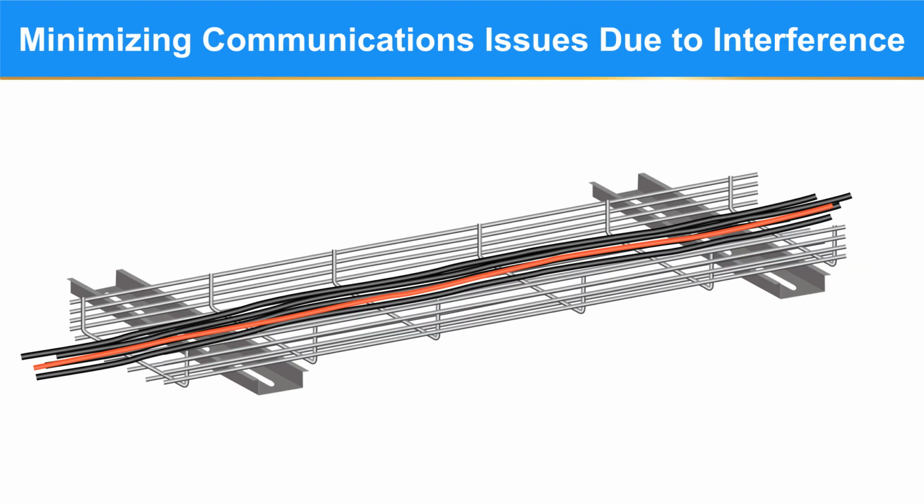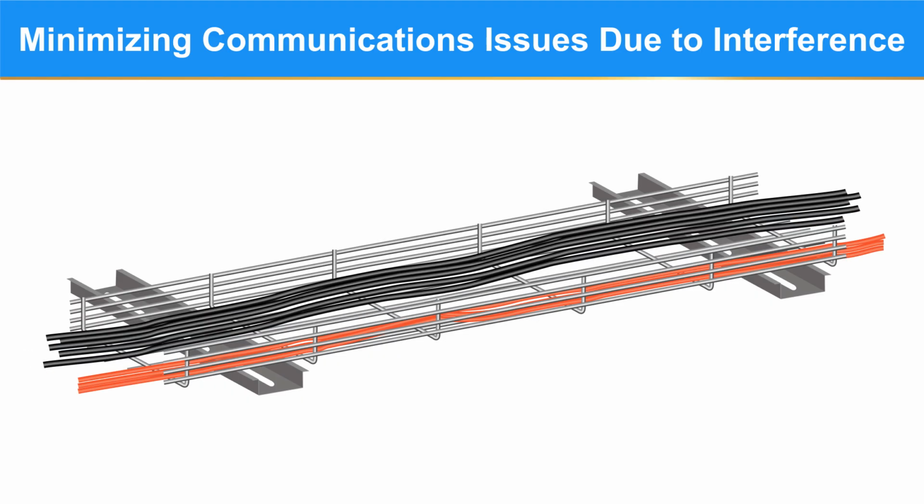One other thing to check is the cable tray the LAN network cable is laying in. It is best to ensure the LAN network cable is not laying in with other large cables that could possibly be carrying high voltage machinery signals. Having the LAN network in a separate cable tray would be ideal, but at a minimum, the LAN cable should be as far away as possible from any other large cables in the cable tray.